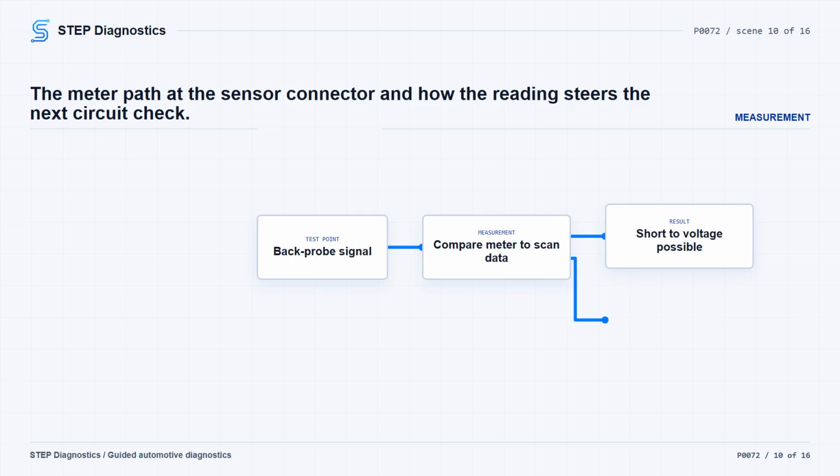If the signal reading has a constant voltage above 6.0 volts, that indicates the signal circuit is shorted to another voltage supply. If the DVOM result points you toward the signal circuit check, disconnect the temp sensor and ECU harness connectors and check the temp sensor signal circuit for high resistance and short to ground.